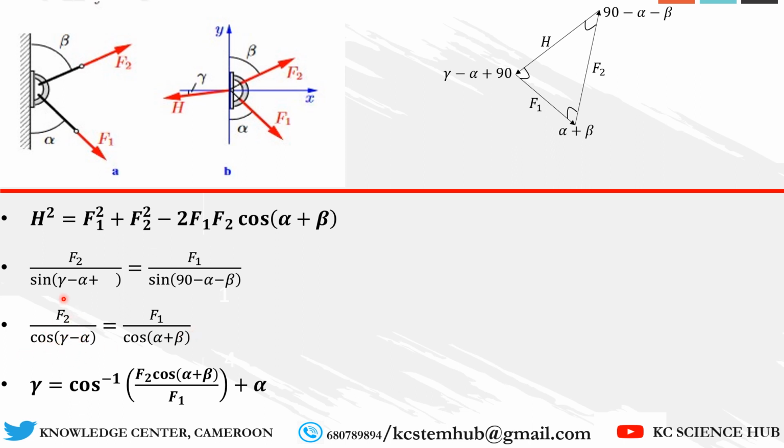And so you realize that I can basically make cos of this the subject. How do I make that? I'll get f2 over f1 multiplied by cos of alpha plus beta, and then I get cos inverse of that, and add alpha to it. I really have to skip some steps here, but I guess you can follow what I've just done. And so this is the result. This is the force that the cables will exert on the eye, and they would exert that force at an angle of gamma from the horizontal.